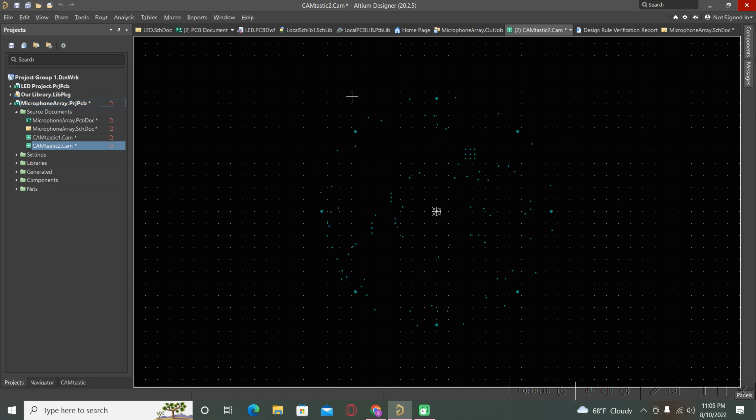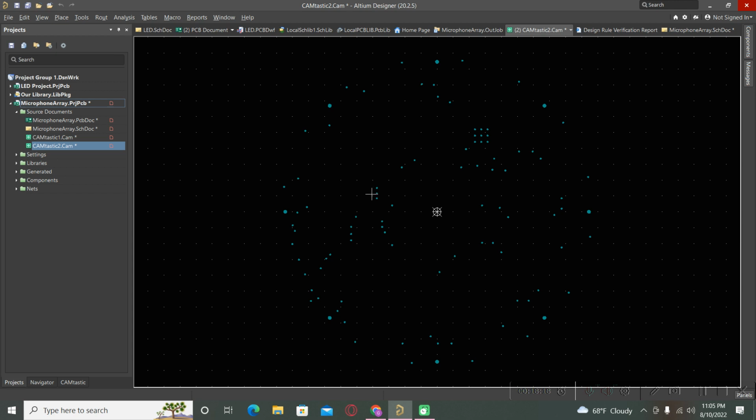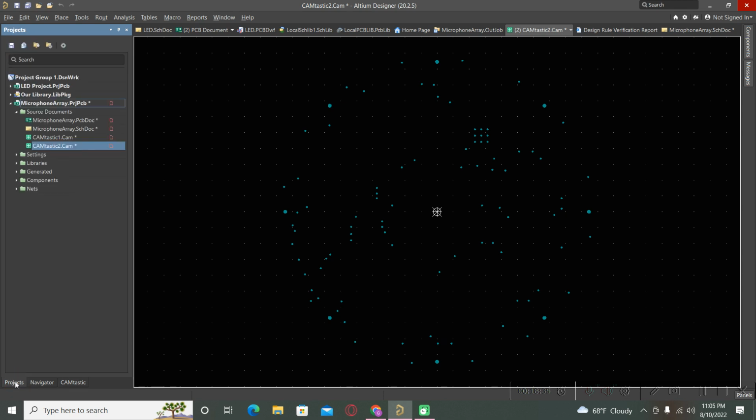As you can see in this CAMtastic file, our information contains only details and descriptions regarding the holes, and for this you have only this text file that contains all the details regarding our board drills and holes.